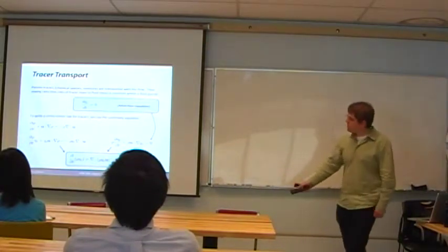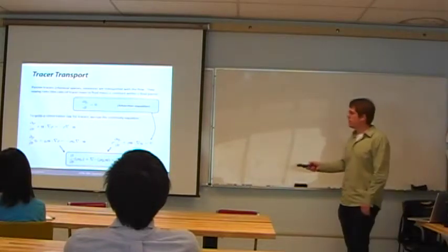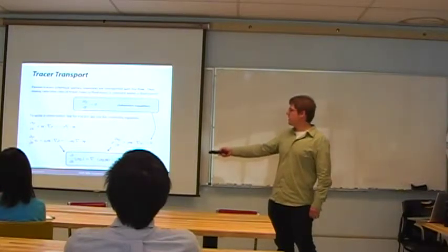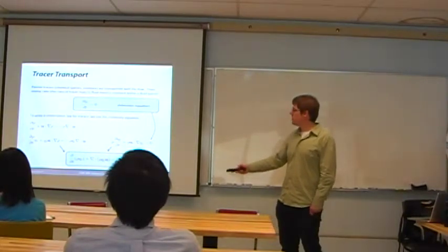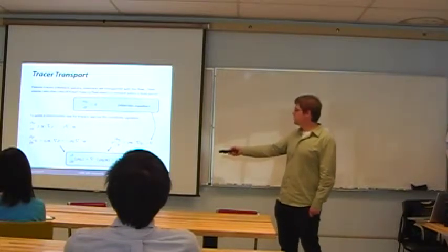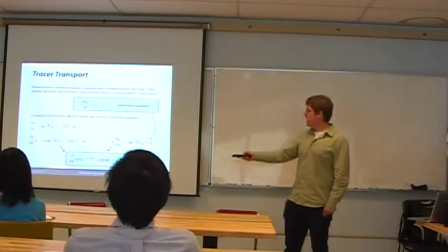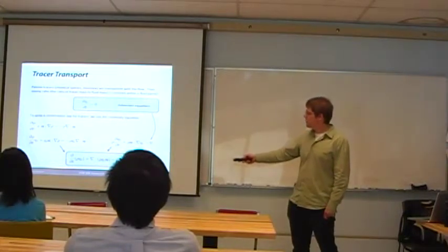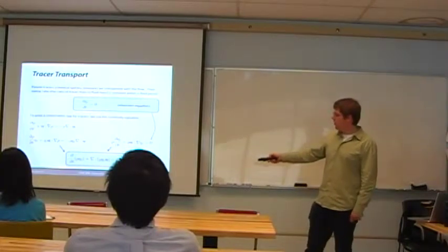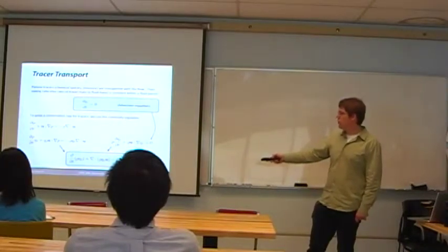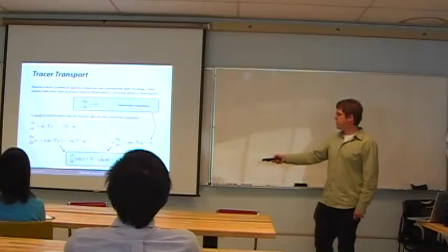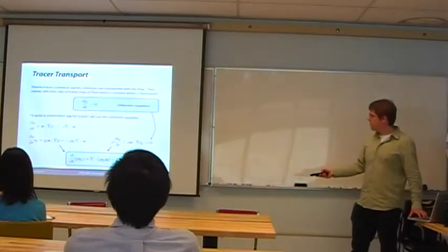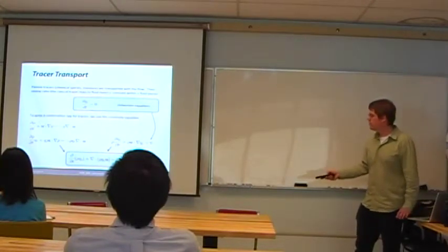This is the same thing from the previous slide, except expanded out in the Eulerian frame. We multiply this one through by qi, so nothing exciting, just all the terms now have a qi term in them. And we add both of those two terms together, and then apply reverse chain rule. You're going to observe that you get an expression of this form, namely the Eulerian time derivative of rho times qi plus the divergence of rho times qi u is equal to 0. So this is a so-called flux form expression for the tracer transport equation.